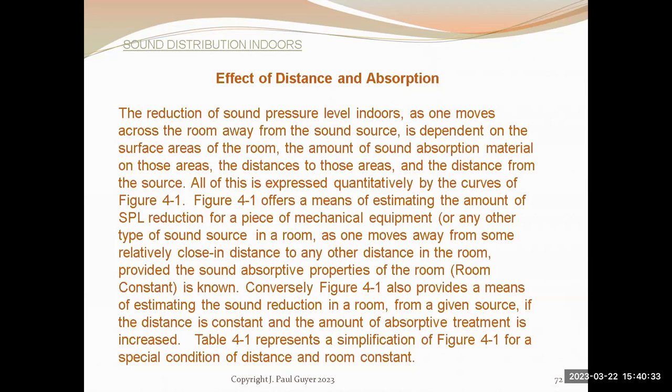And then the wall structure is set into a vibrational mode. That solid structure then impacts air molecules on the receiving room side, and the acoustic energy is transmitted from molecule to molecule until it gets over to the human ear in the receiving room and begins to vibrate against the eardrum.